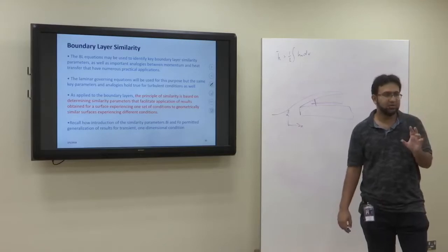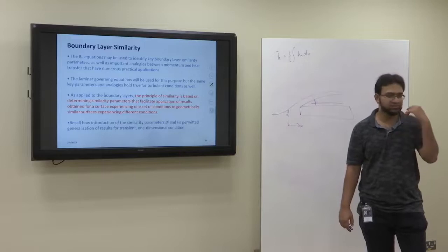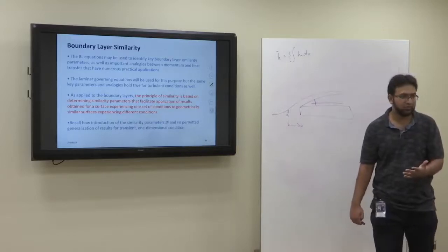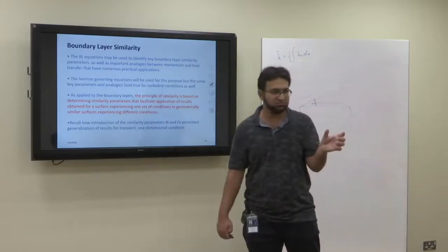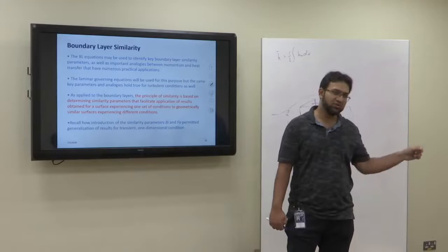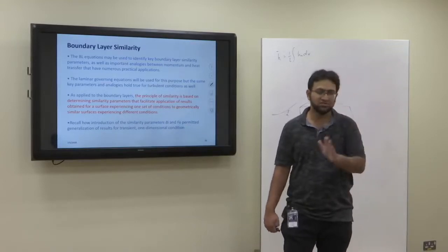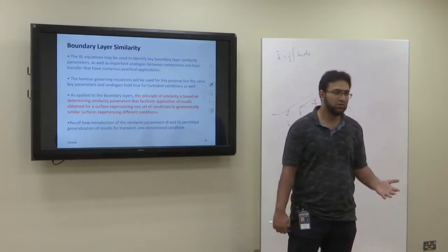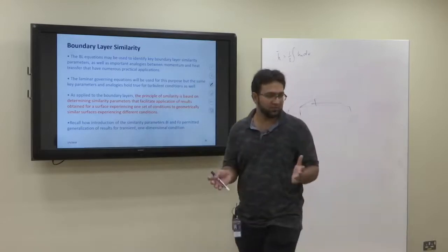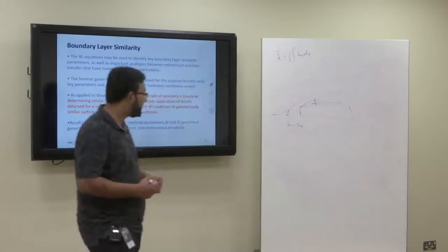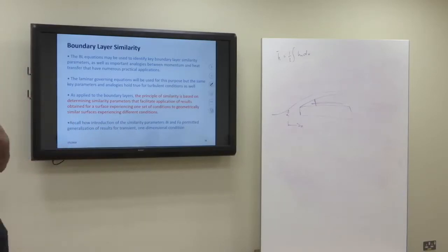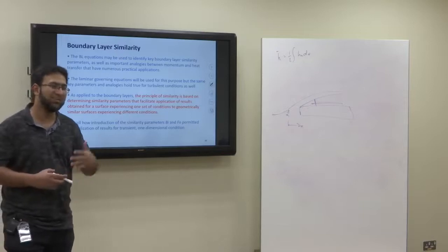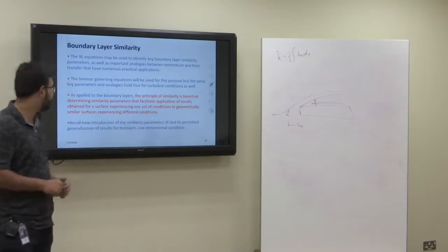it's actually just the Reynolds number on which you have to focus. Whether it's honey, water, alcohol, blood, whatever it is, any fluid. If you just know that the Reynolds number is below this number, then we know that it's laminar, it's smooth flow. If it is above this number, we know that it is not smooth flow. So it becomes independent of all these parameters, okay? So by similarity, we develop these kinds of dimensionless parameters, which help us analyze problems in a much better way. We're independent of fluid properties, things like that.